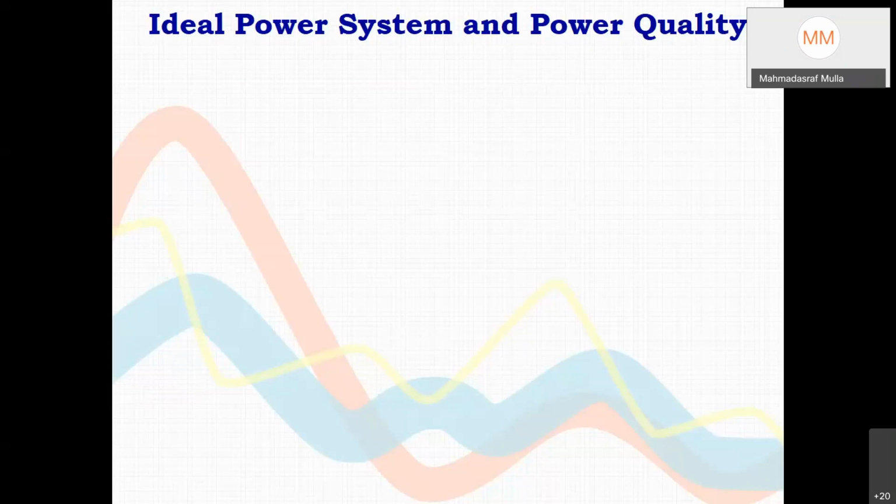So the other point is that both voltage and current should be in phase with each other. Yes. If we can make voltage and current in phase, then volt ampere will be equal to wattage, and our transformer capacity is in volt ampere.